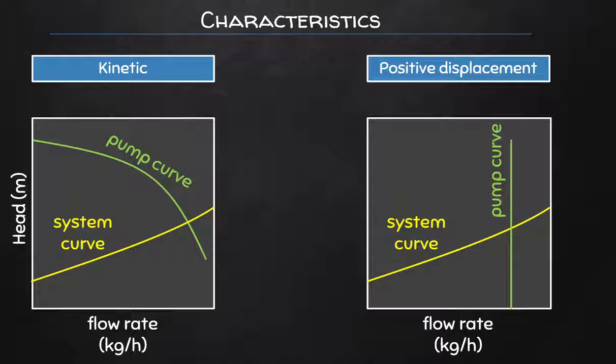In the case of the kinetic fluid movers, which are in general the pumps that you would likely see in industry or even if you go to a hardware store, the characteristic curve tells us how much fluid will be obtained in terms of a flow rate, a mass flow rate, or a volumetric flow rate at certain pressures. Now, usually it's specified in volumetric flow rate because you don't know what mass you are going to be pumping around. You know, it could be water, it could be oil, who knows.